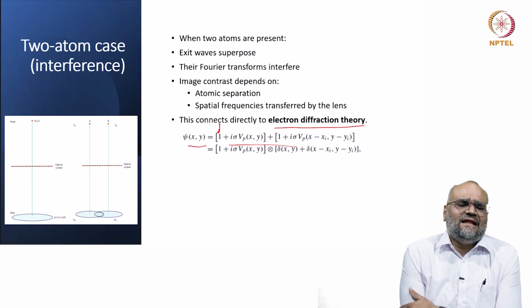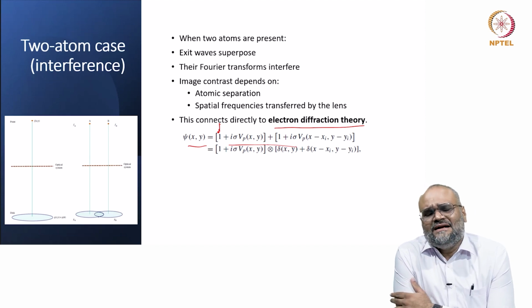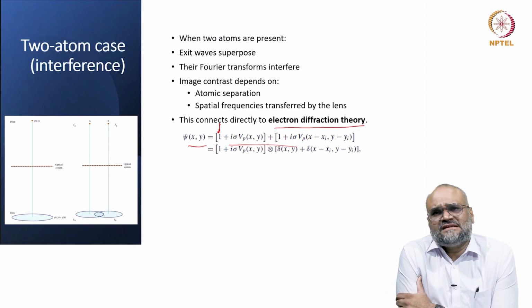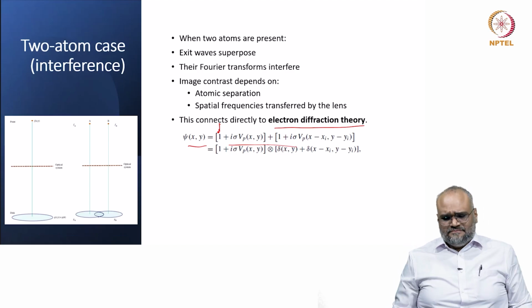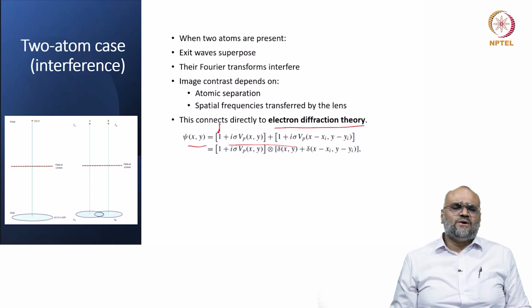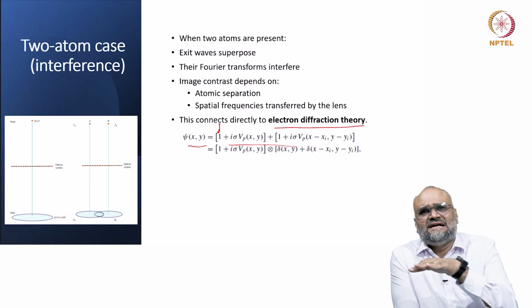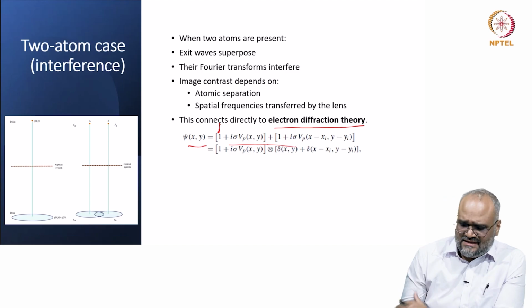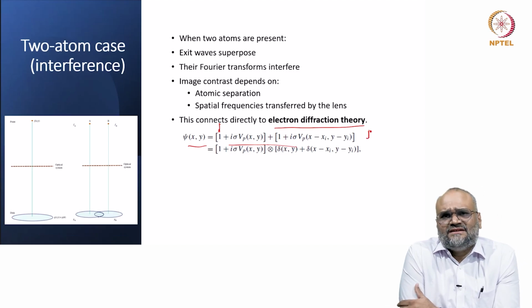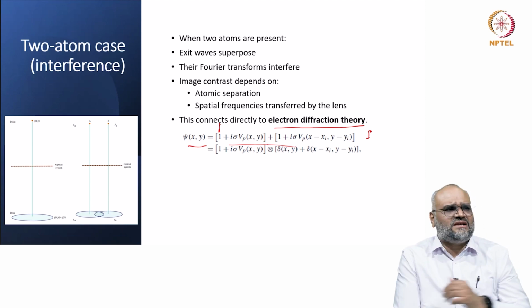So the electron wave that interacts with the specimen modulates the phase of the incoming electron beam, and in terms of the spatial positions of the atoms that are sitting within a crystal, you are varying the electron phase, and you can relate this phase to the potential associated with the positions of the atoms which are sitting in two dimensions. The third dimension of the thickness has been ignored in this particular equation that is shown here. When you take really thin objects, you can always use this kind of an approximation, and this is called the weak phase object approximation.